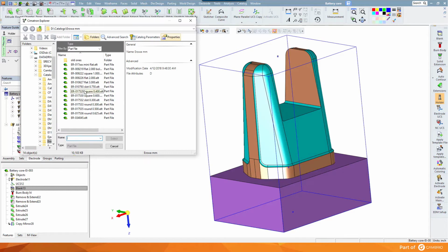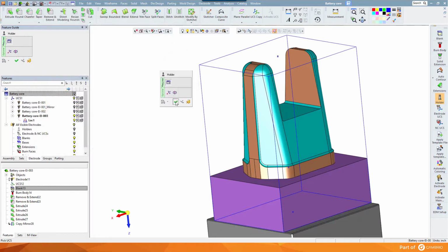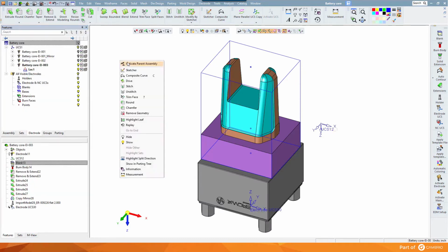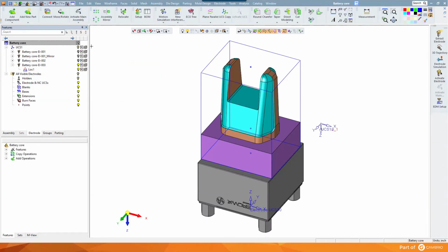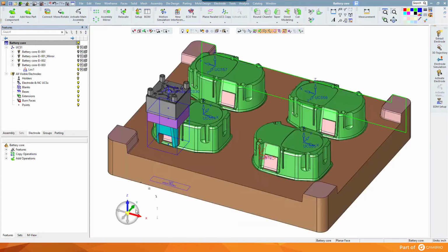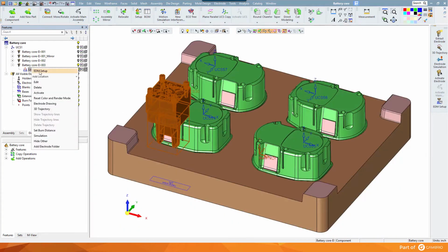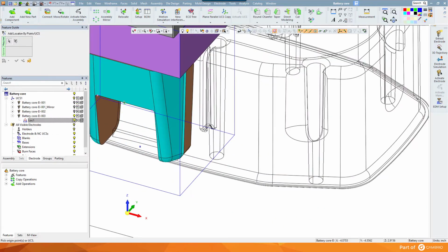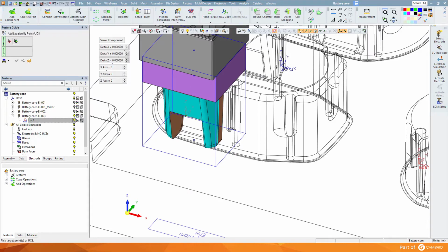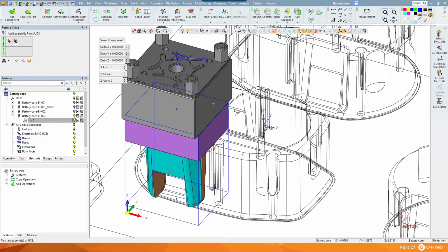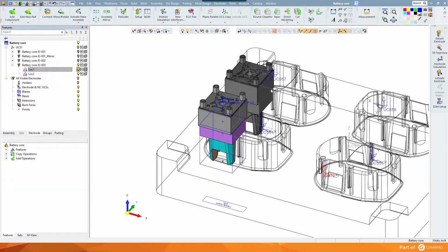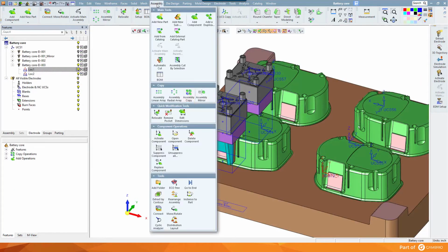Now we're ready to select a holder and place the electrode user coordinate system. Let's add the other locations. I'll use the option by points and select a single anchor point on the electrode to match to the core. This is a fast way to add locations that don't need to be rotated. Then I'll use assembly copy and add it to the other cavities.